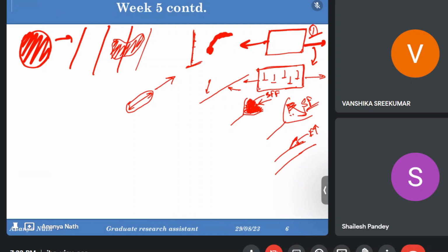But for this cross slip, I am telling you that it's easier for the screw to cross slip than for an edge dislocation to climb. There is a pile up of dislocations; it's not a single dislocation. Ma'am, for a single dislocation, if we see in terms of distortion, the energy of the edge dislocation is greater than the energy of a screw dislocation. Yes, yes.